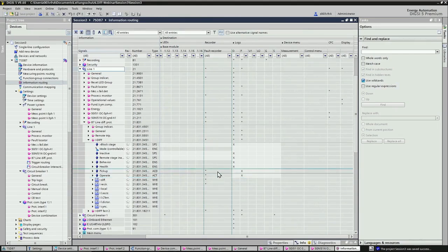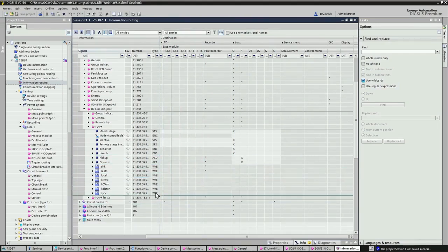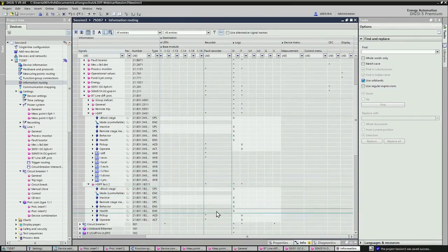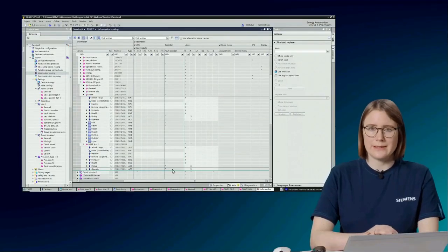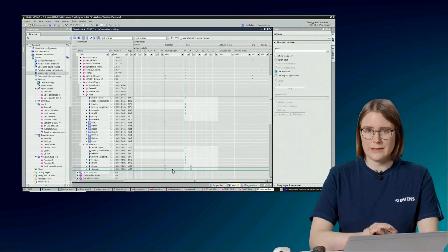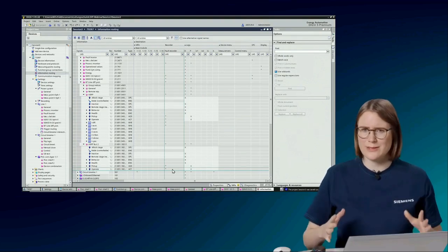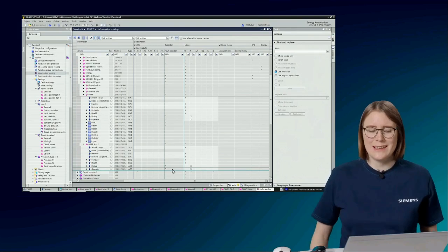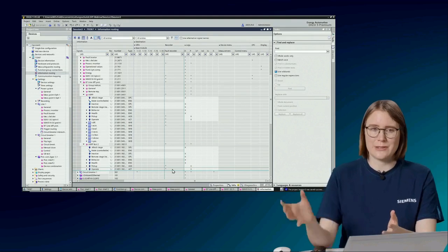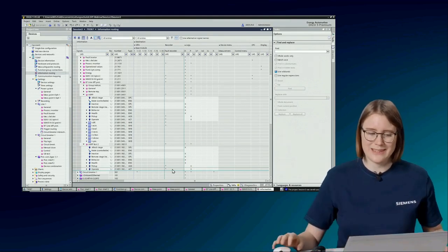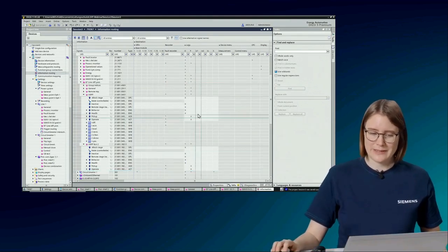Also, it makes sense to see pick up and operate for the IDIF and the IDIF fast 2 stage. You see at the moment here, these signals are already assigned to the recorder, and this is a DIGSI feature since DIGSI version 9.60, that even if you insert the function newly from the library to the device, then these routings are done automatically.